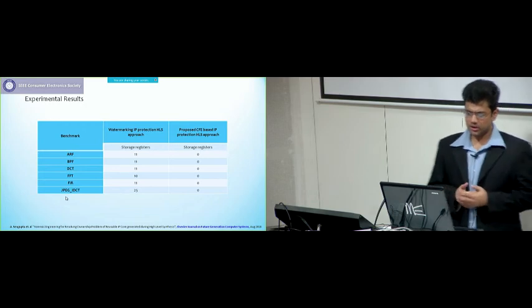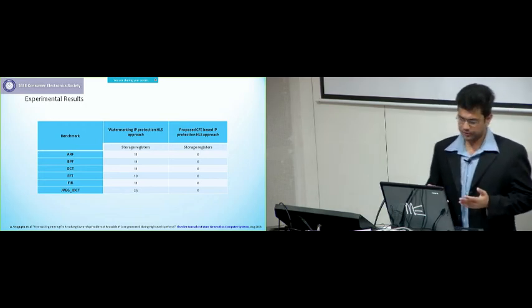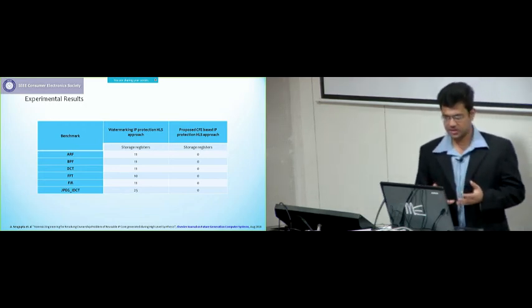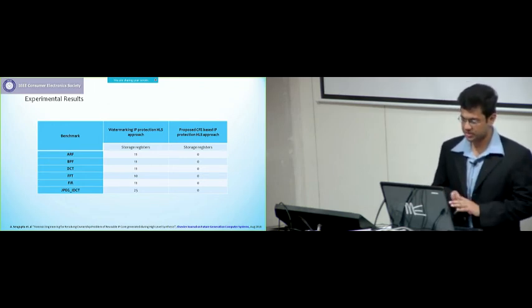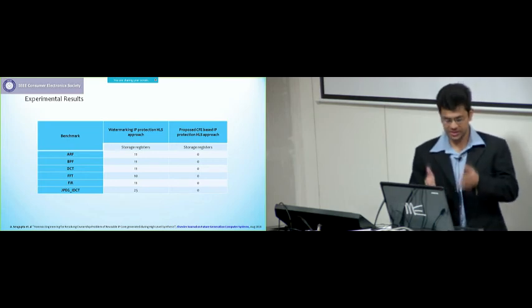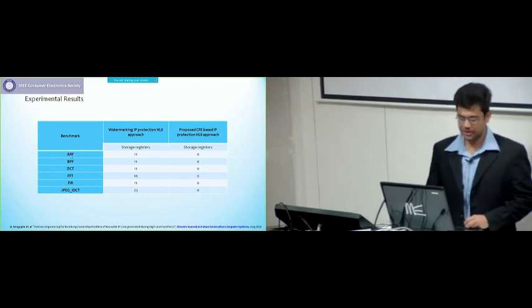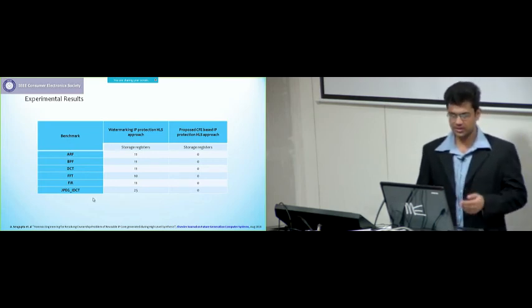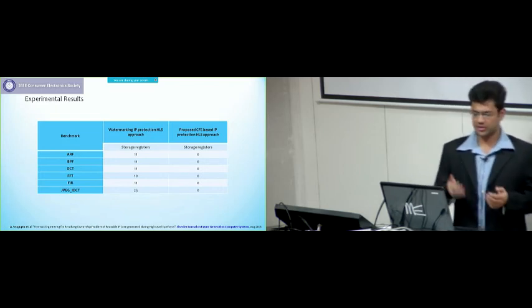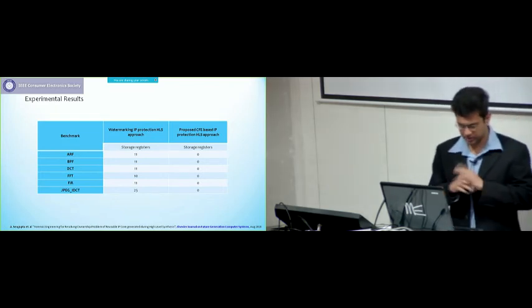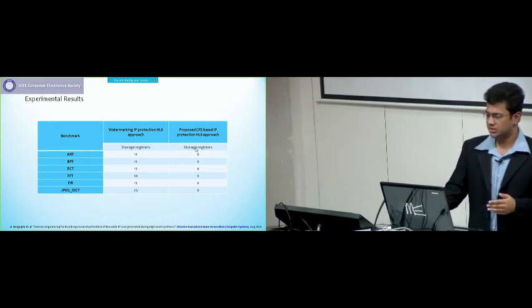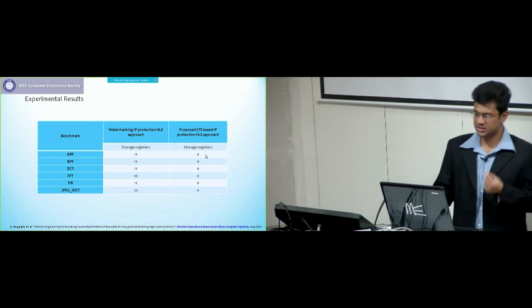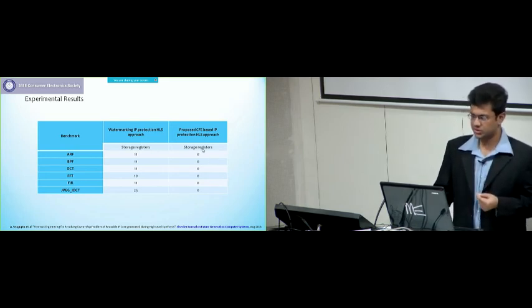I have also tried to put a comparative study of the hardware features in terms of the storage variables used in watermarking, IP protection based methods and the proposed CFE based methods. As you can see, for all of these DSP applications that have been tested here, starting from filters to JPEG to fast Fourier transform, DCT, whatever it is, in all of these individual benchmarks, the proposed CFE does not consume a single storage register. Therefore, the hardware overhead is completely 0 compared to watermarking.